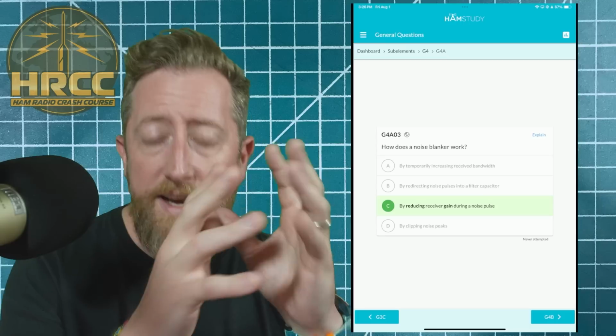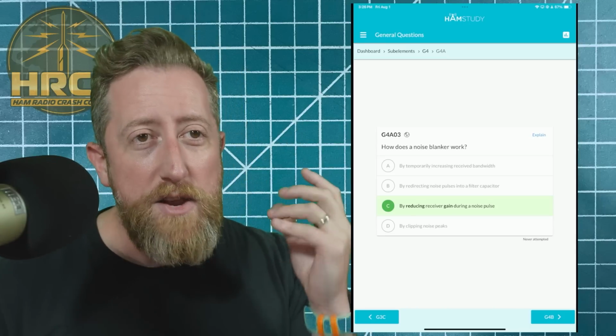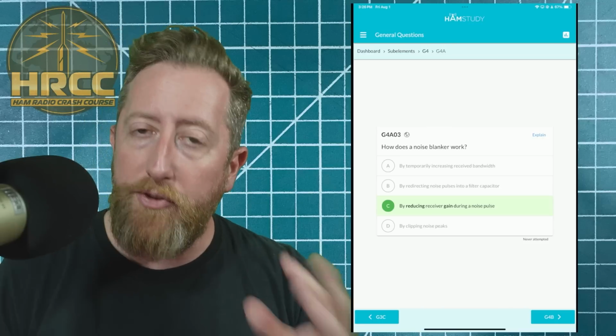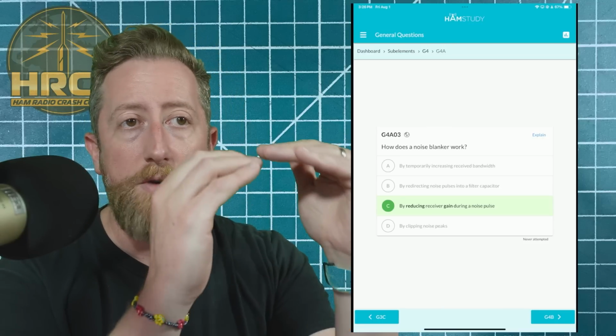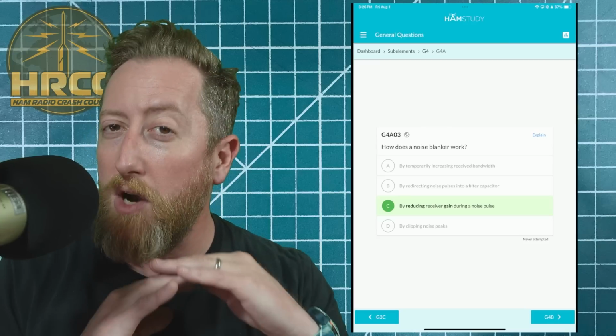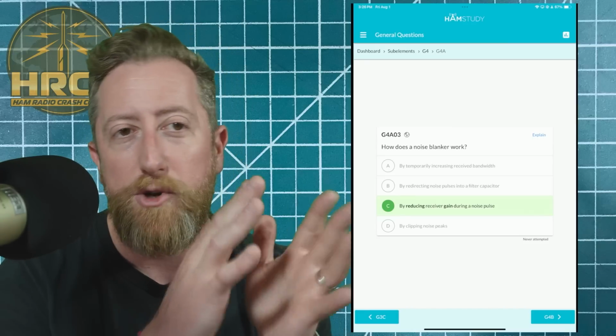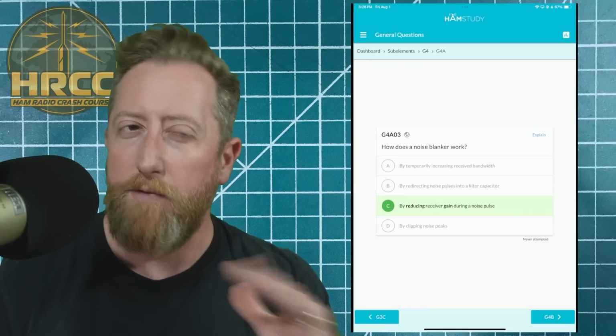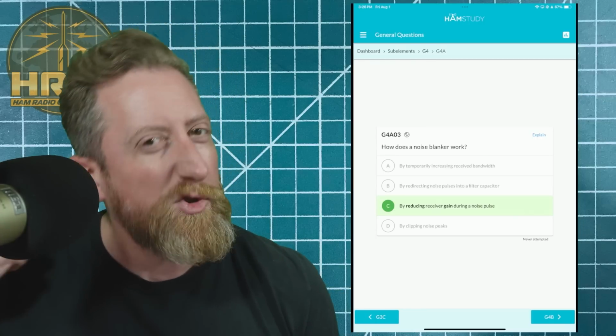So if it's a voice and they're kind of in the noise and you think, oh, I'm just going to hit the noise blanker and that's going to take away the noise. Well, no, the signal you're trying to hear is a part of that noise. So sometimes, even though it can be a little abrasive on the ears, it's best to try to not use any filtering first before you try and turn on the noise blanker or see if you can improve it via some kind of audio processing, at least to train your ears a little bit.